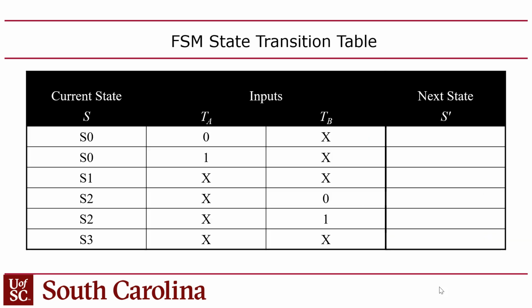Okay, so how is this implemented in hardware? So I mentioned earlier that a state machine is comprised of some combinational circuits and then some registers. So the question is, how do you assemble everything together to make this work? Now obviously, if you do a state machine in Verilog, a lot of these truth tables are generated for you as part of the synthesis process, but this is explaining how that works. So basically you need to have a next state table, right?